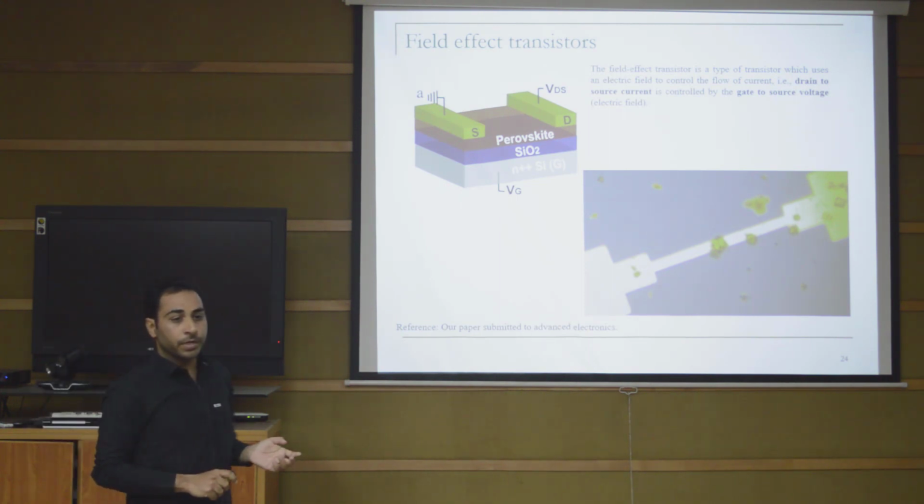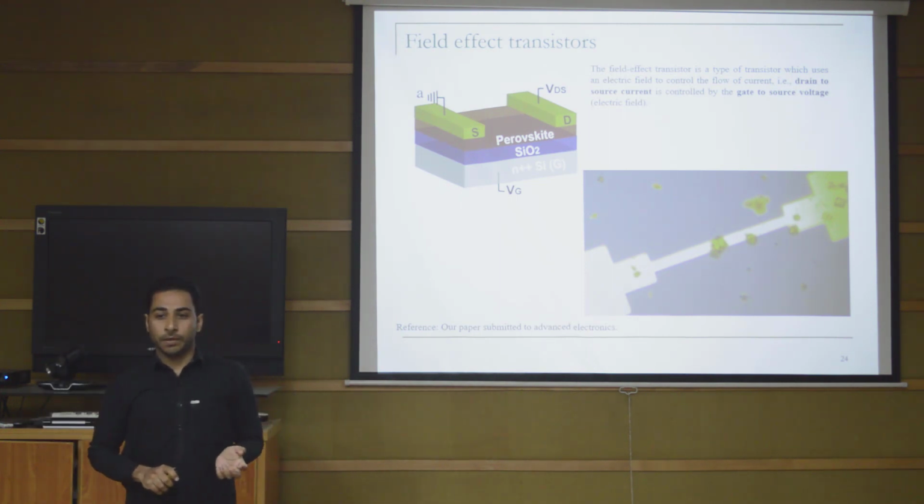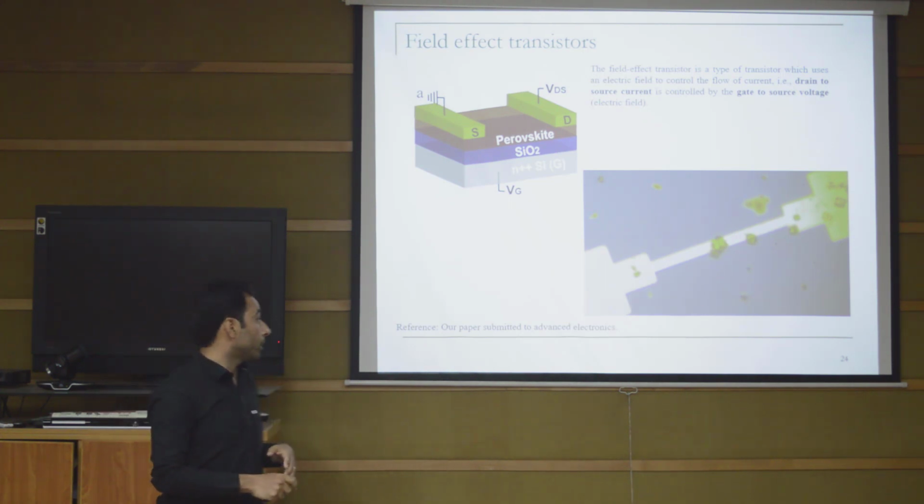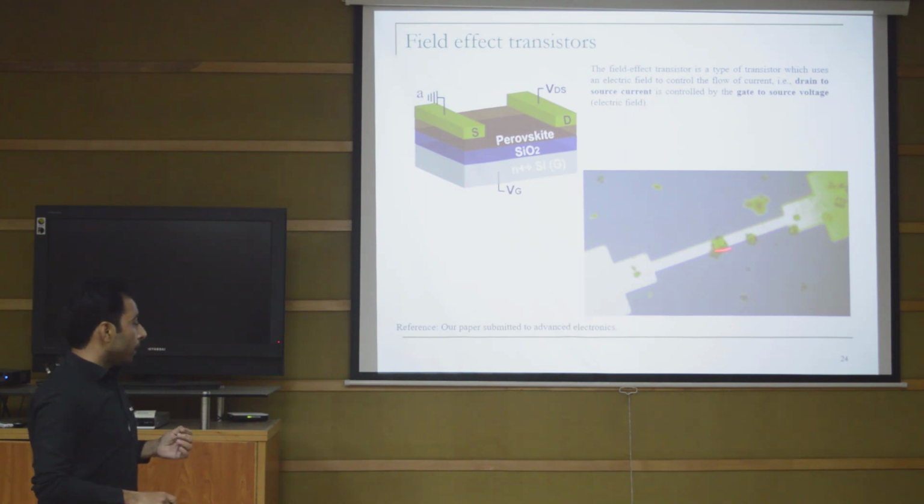This distance must be less than 20 microns, otherwise the electron and hole will not be able to reach the respective electrodes. Here in our lab we have utilized lithography techniques, where we have separated one small sheet of 2D perovskite, and then we have fabricated the gold electrodes upon it.